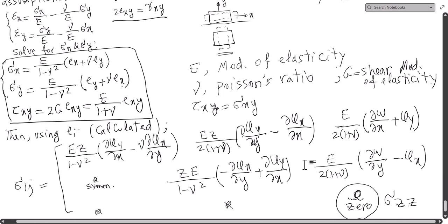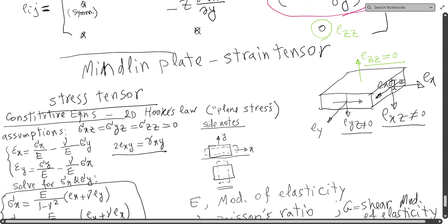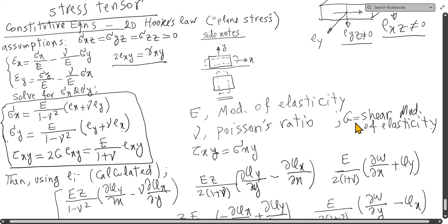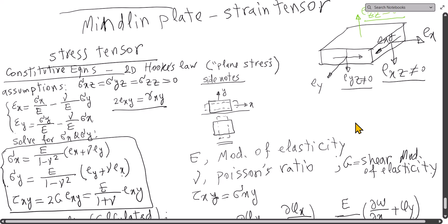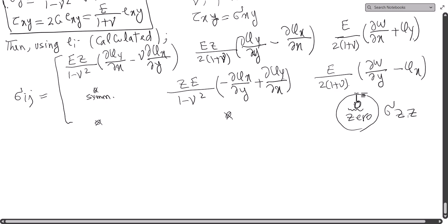Okay, so immediately we see some issues here. We have recovered the in-plane shears as I sketched here, sorry, the transverse shear, but we get some issues with the normal stresses on this plane. Why is this an issue? Because if you have a traction applied on any surface of the plate, then this says that it is 0. So we have to do some recovery for these things.